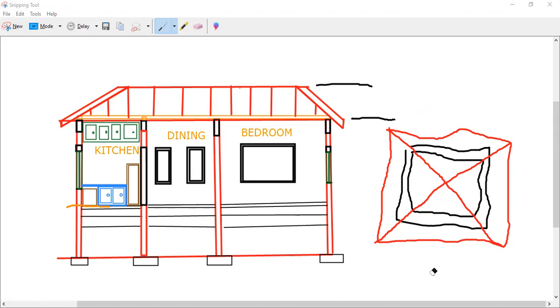It changes from that to that. Draw a line at 30 degrees to get the pitch for the roof. I would then need to go back to where the cutting plane line is. In that case, that means a thicker line and a different color. Let's use green. So if the cutting plane line is here, if you cut the building here, and we are looking in that direction.